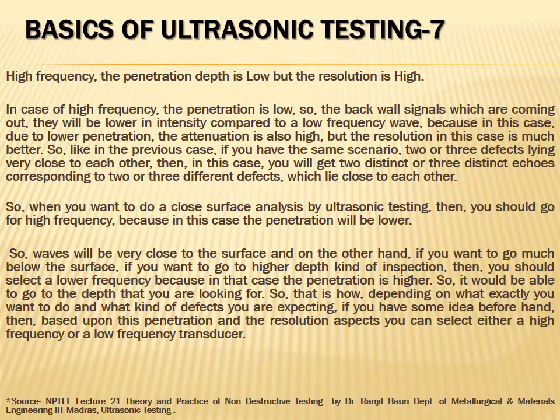Depending on what exactly you want to do and what kind of defect you are expecting, if you have some idea beforehand, then based on the penetration and resolution you expect, you can select either a high or a lower frequency.